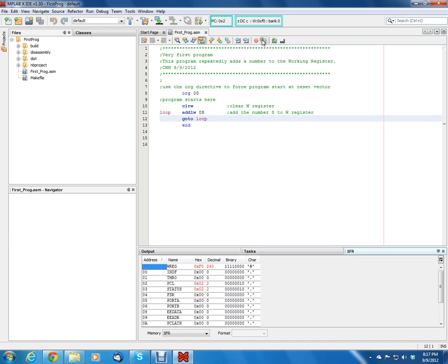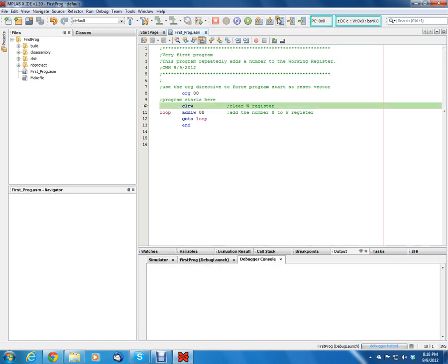Now, in order for us to really step through this code, we want to step line by line through this code. Also, I want to reset, because this code was running just back and forth, and this random value wound up in memory. So let's see if we can reset this. The way to do that is instead of clicking here, you have to click on the little triangle and say Launch Debugger instead of Debug Project. I don't really know what the purpose of that is, but Launch Debugger is going to give us our little menu button, our ability to step through the code.